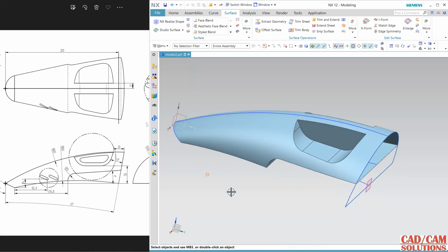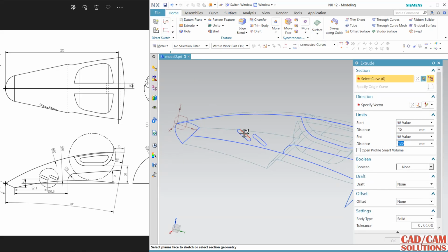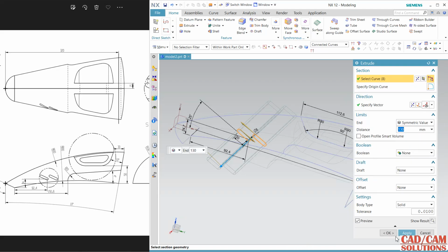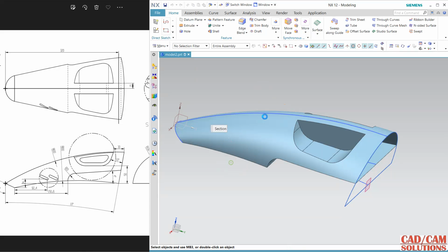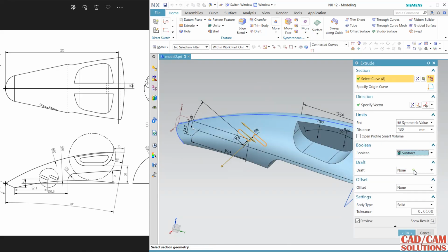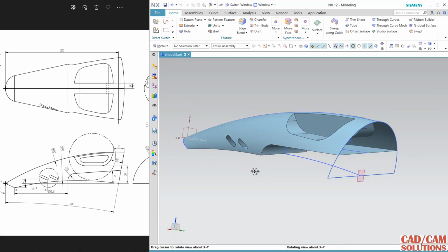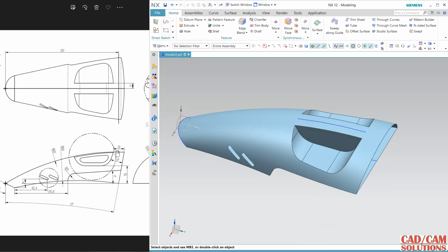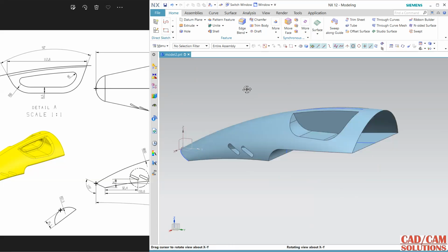And one more curve I have drawn, this smaller one, so use extrude for this one and this one, and go to symmetric and okay, and in shading, right, so double click it and use subtract, it will automatically cut this, right. Now hide this one and this one as well.